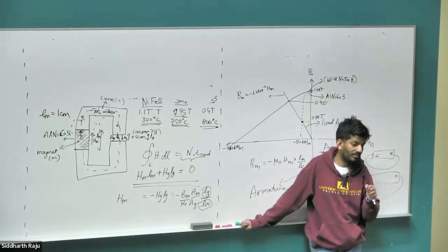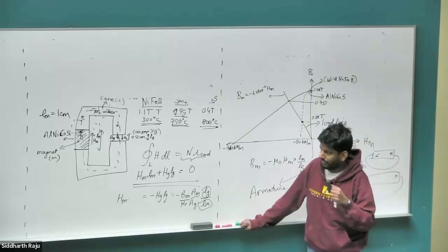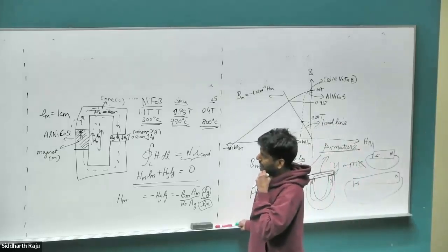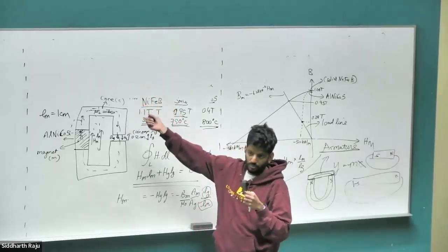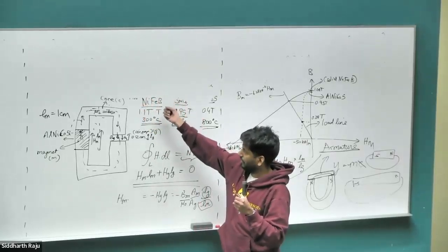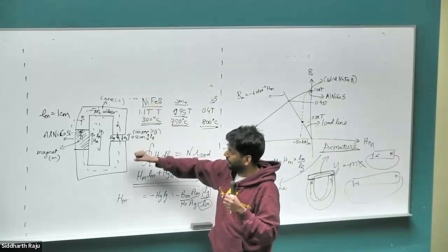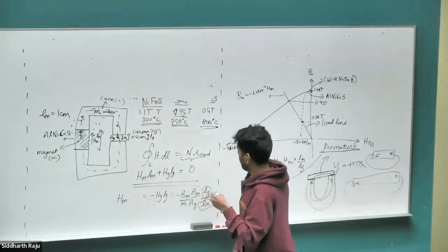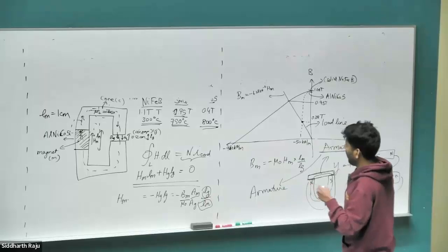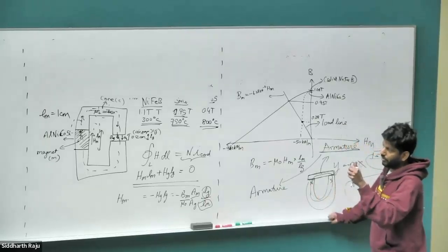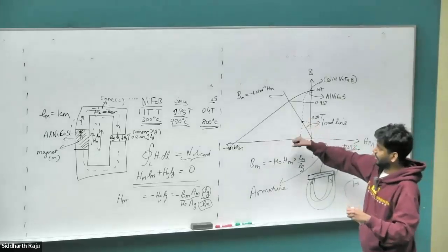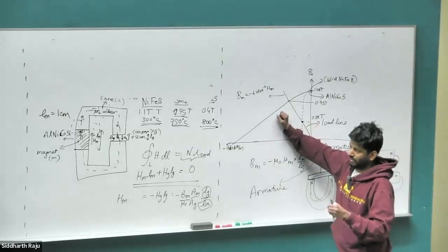Ferromagnetic. Ferromagnetic. It's somewhat intuitive, right? The thing that you have put in your neodymium magnet is iron, a known ferromagnetic material. Cobalt is the only thing missing. But it should be ferromagnetic. But that's where intuition most of the time ends up being wrong. It is not. Magnets do not behave like ferromagnetic material. In fact, Alnico behaves somewhat like a ferromagnetic, while neodymium behaves like an air gap.